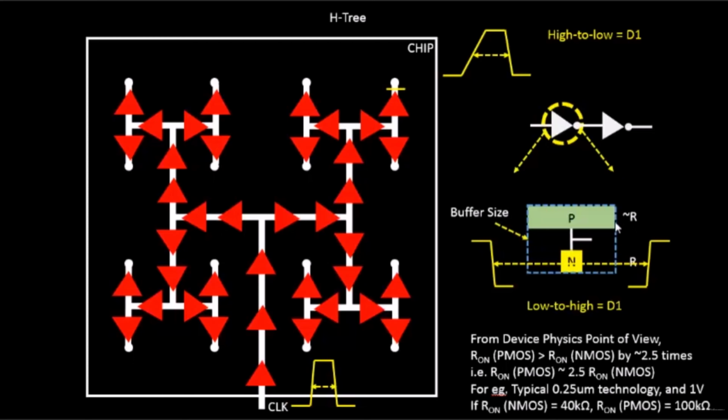a result of that we got a similar discharging and charging time, basically the rise time and the fall time. So we got an equal rise time and fall time. So why exactly did we get that equal rise and fall time? That is because the time required to discharge the load and the time required to charge the load, we balanced that particular time. We got an exact time for the charging and the discharging time. That's how we got the solution to the unequal rise and fall